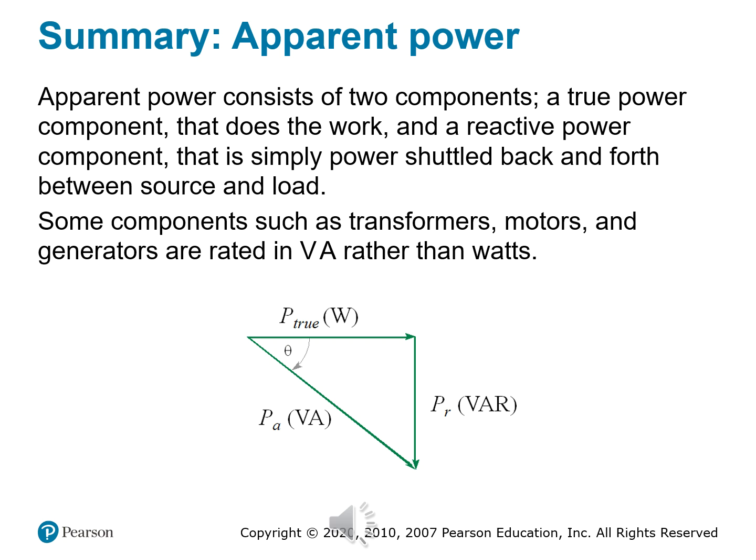What is apparent power? We label it as P sub A, and this is the total power supplied by the source to an AC circuit. It's measured in volt amperes, VA. And here's a trick to this: not all of that power actually gets used. Apparent power is made up of true power, P sub T or P sub true. We measure that in watts.